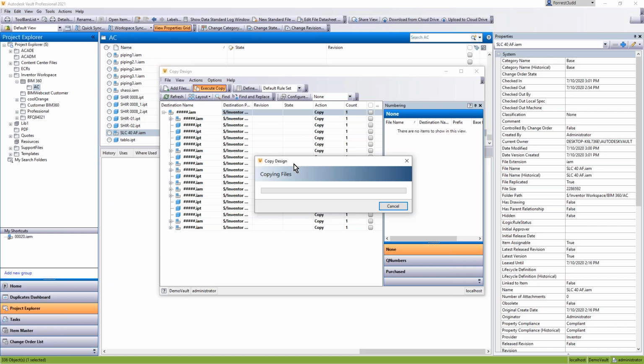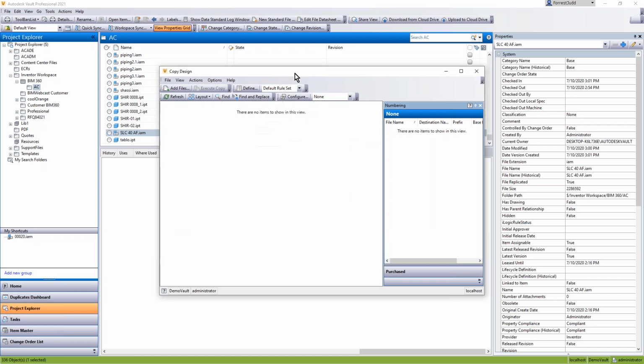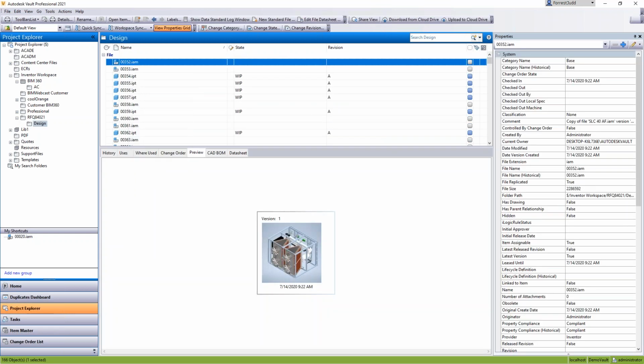And we're going to take a look at how you can do that in Inventor using the shrink wrap capability. It gives you lots of powerful tools to decide what gets included and what doesn't. And again, the more you can take out while still maintaining what the architect needs for space claim and hooking up services to it, the better. Right. So we'll just get this opened up in Inventor.